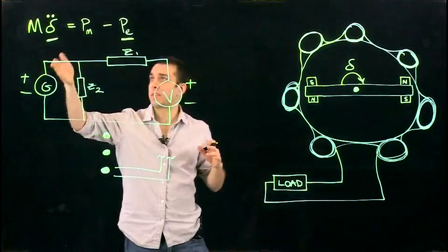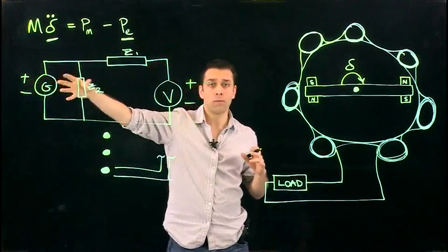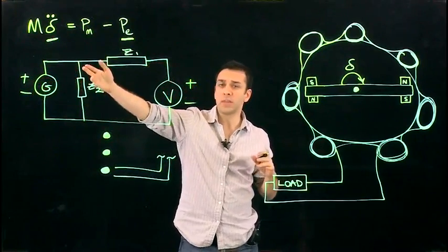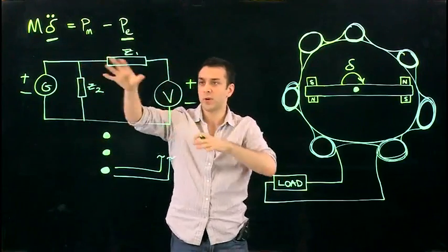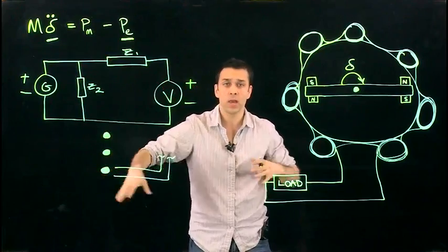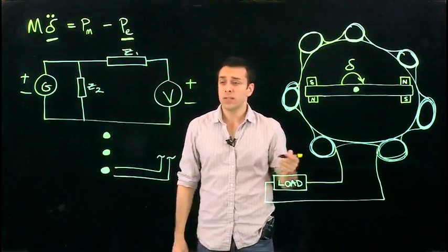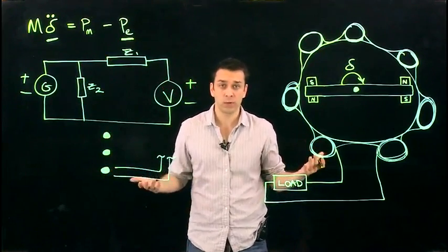And so we've got the swing equations, which model the power flow through a generator. Using matrices and linear algebra, we can stack together all these differential equations that we get from each of these diagrams and simultaneously solve them to get all the states that might be of interest across the system.